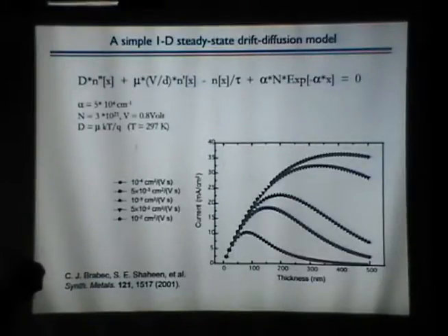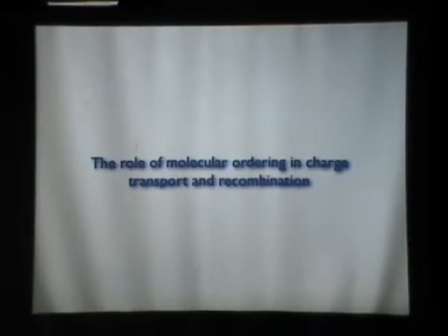Now what this model fails to include is that this recombination term, tau, also depends on mobility. The Langevin process, which I just mentioned, has mobility in the recombination rate. So tau goes down as mobility goes up, and that can decrease the current. In the more advanced models we include those terms. So anyhow, this is a basic picture. Fast carriers are generally good.